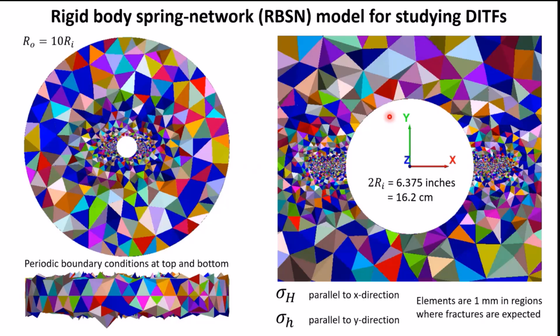In XSite, the fracking tool of ITASCA, they developed a really neat method based on the J integral around the fracture tip, and then you can determine, okay, does the fracture propagate or not? So you can set the fracture toughness there, but you still have to integrate around the tips to get the stress intensity factor. I'm not doing that because I've got a fracture toughness which is quite realistic, because I'm doing grain-scale modeling, basically.